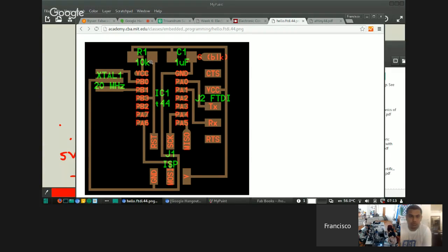See, there are two resistors we use. One is pull-up and one is pull-down. So when we connect an LED, we put a resistor to limit the current, right? So that's a pull-down resistor. We connect it to ground. This is something similar, but instead of ground, we are connecting it to VCC. So PB3 will be normally high, and when it is activated, it goes low. So that's the purpose of that pull-up resistor.